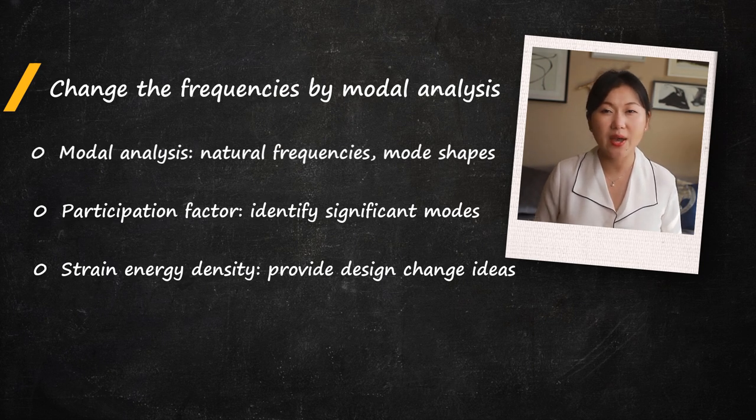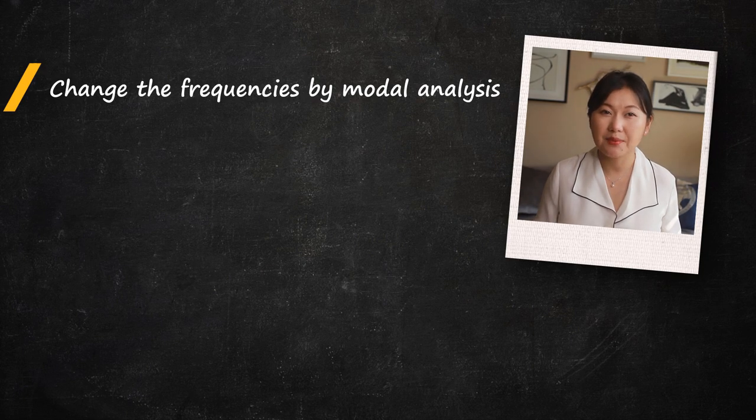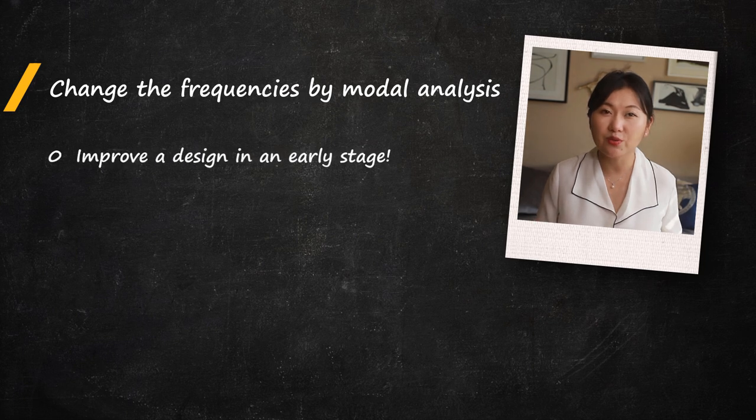That is, where to add materials to increase the stiffness or where to remove materials to reduce the mass. Thus, the modal analysis results, though being relative, give us information regarding the dynamic response of the system well before we perform more computationally expensive dynamic simulations. The modal analysis can be used as a quick way to improve the design at the early stage.